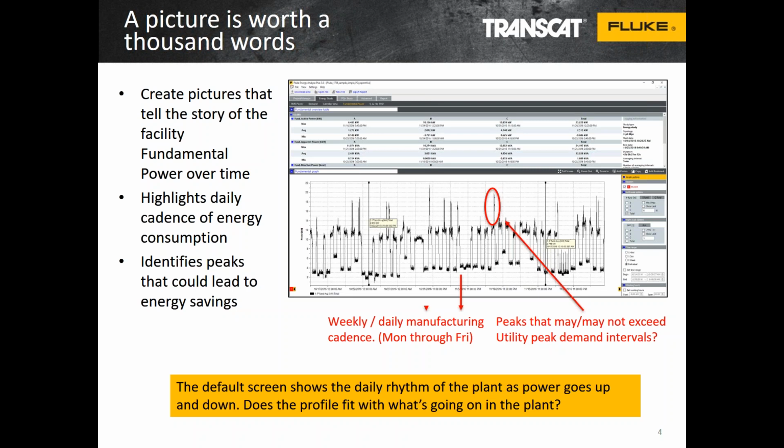It's not just a penalty based upon paying for that extra energy. There is an additional penalty on that, and often that would go on for a full 30-day period. So the utility would charge you at that higher rate for a full 30-day period. Typically, these peak demand processes look at something like a 15 or 30-minute period, and they will measure the kilowatt hour over that period. And the benefit for the facility to take up that kind of tariff is that they get the energy at a better price, because they're committing to taking a certain level of energy from the utility, which enables the utility to plan their network better.